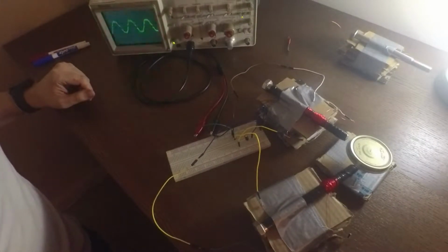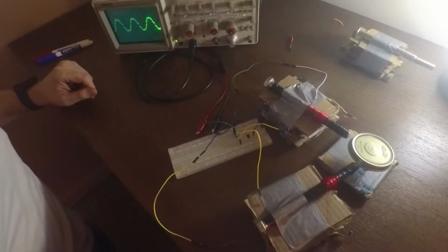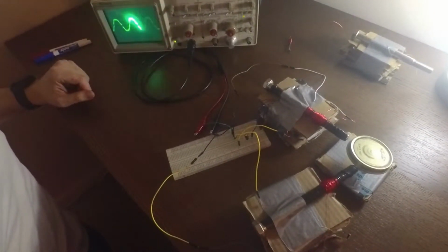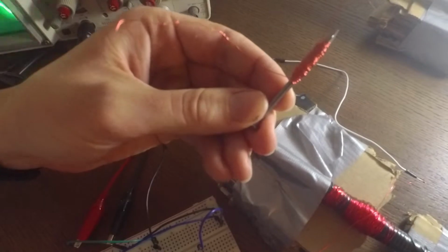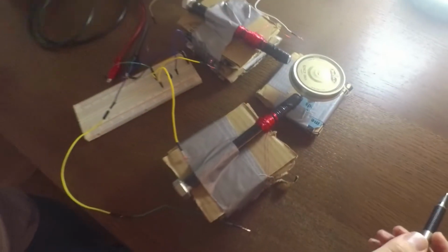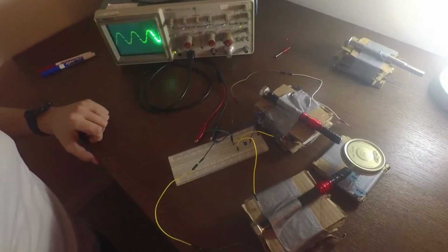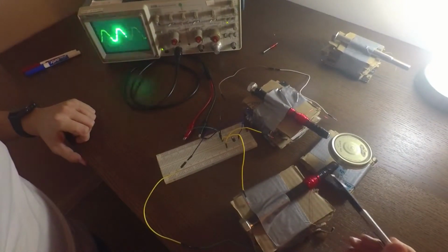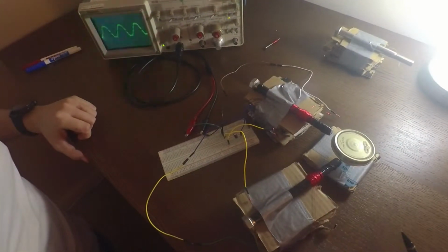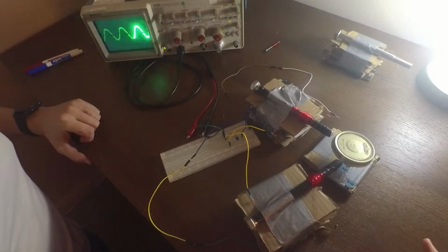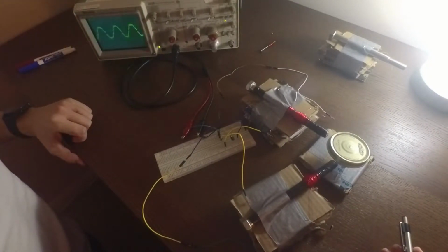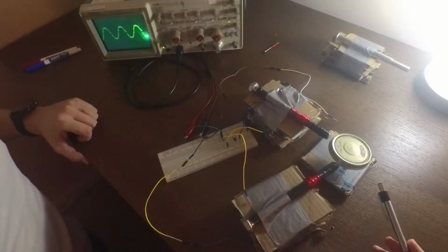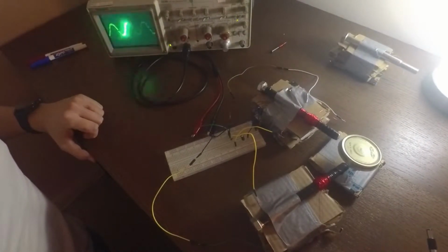To try to resolve this issue, I rewound the coils using a different wire source. I also tried to modify the winding interface using smaller bolts, as well as with and without electrical tape. The thought behind using electrical tape was that it would prevent the bolt from shorting out the coils. I have also tried various objects as the rotor, such as half a soda can as well as lids that I had in my fridge, to see if the weight or material was causing an issue with the operation.